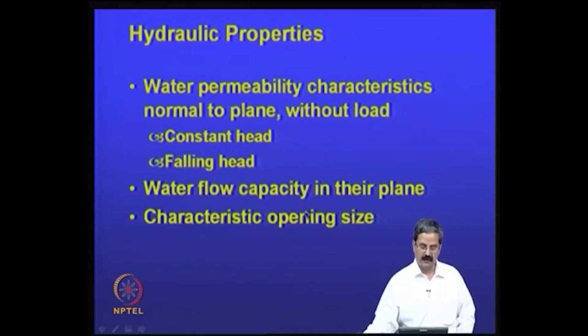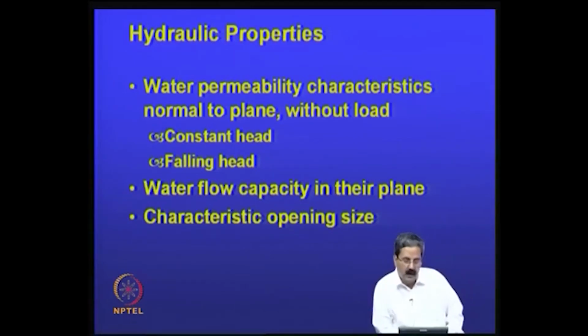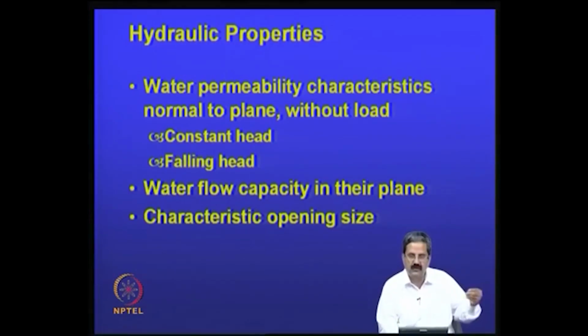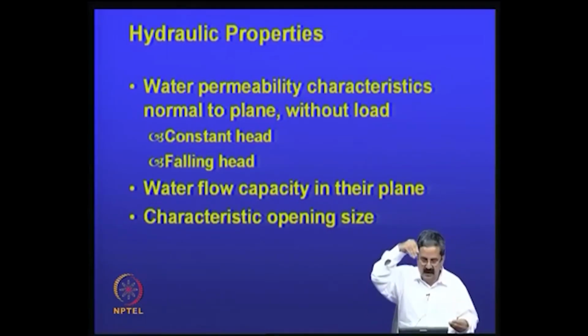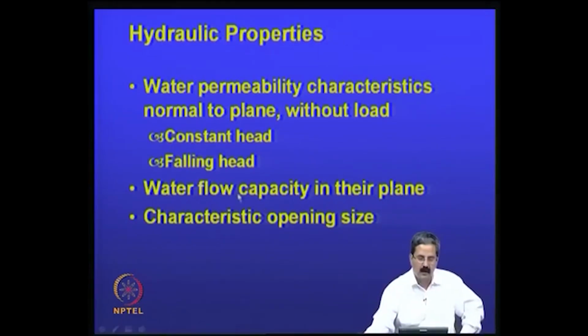Then another important property we should look at is the hydraulic properties, the water permeability characteristics. As I said, filtration is when the water flows through and only the water is allowed, not the soil. For this we have simple tests: the constant head permeability test, the falling head type of test, and the water capacity in the plane. We calculate its flow capacity also.